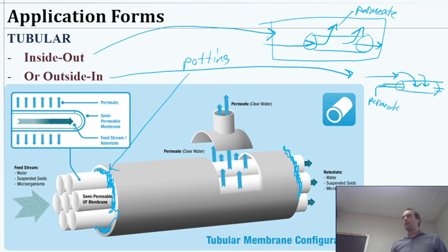As I say that, I realize I haven't shown you yet, but typically in a tubular membrane, if we take a very close look, we'll typically have a separation layer that has very small pores, and then larger pores to let water through much easier for the rest of it. So we're going to put that separation layer on the inside or the outside based on which way we're doing the flow. I think we'll probably talk a little more about that next time since I'm dealing with these slides first.